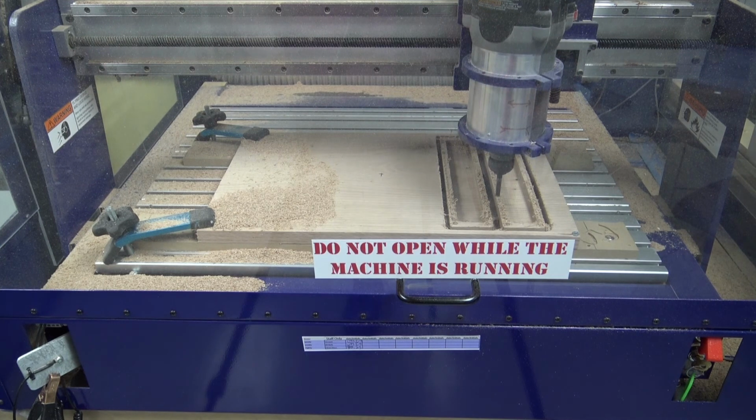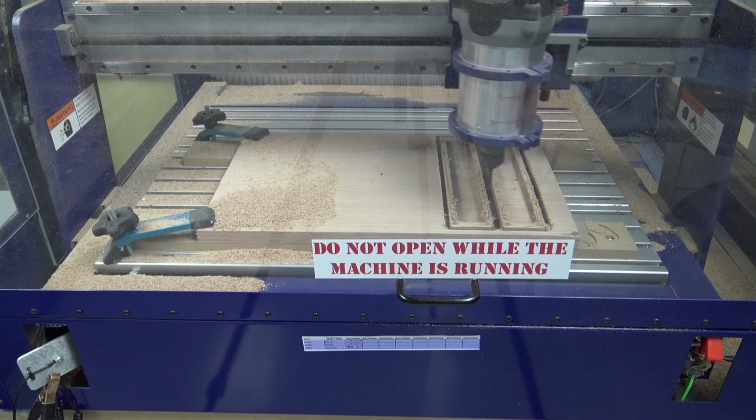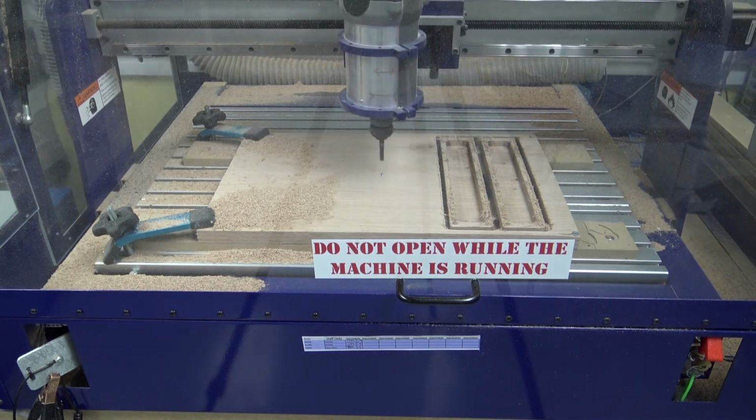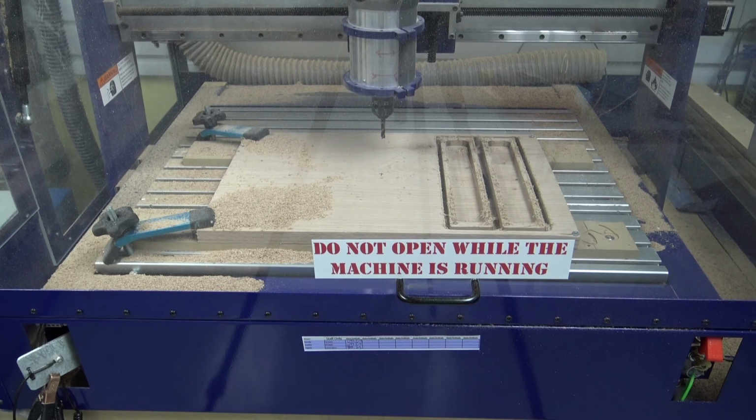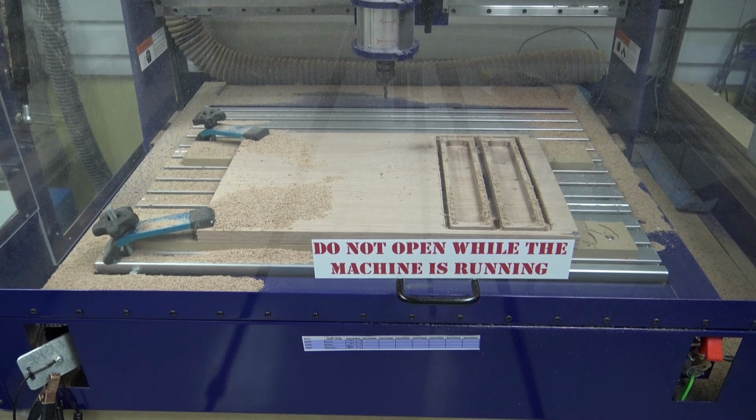Once the machine has finished its final cut, it will move back to its central location. Use the yellow movement box to guide the bit to the back of the machine so that we have access to the stock with relative ease. Since we will now be opening up the door to the machine, it is important to remove the key. And also, to ensure power is off to the machine, press the emergency stop button.